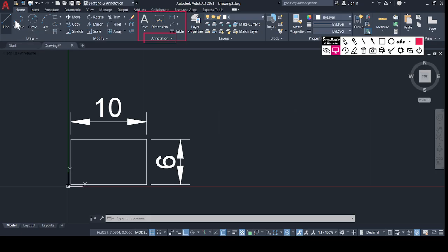The first difference is, you can see this drawing has been created by line. Now let's take an example of the same drawing with polyline. So either you can go over there for the polyline command, click on this, you can see the PLINE, or the polyline command will run, or there is the shortcut key PL enter. So the polyline command will be started.